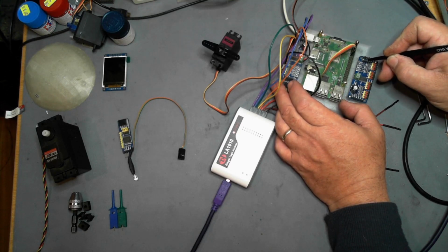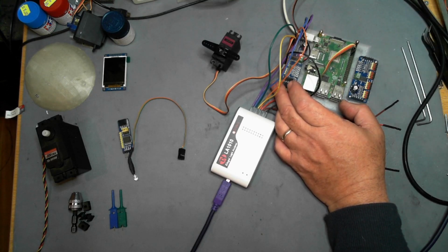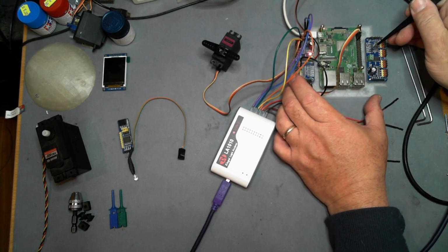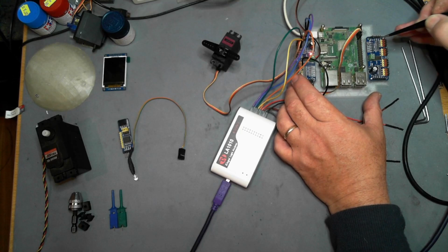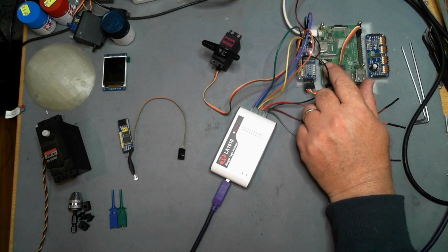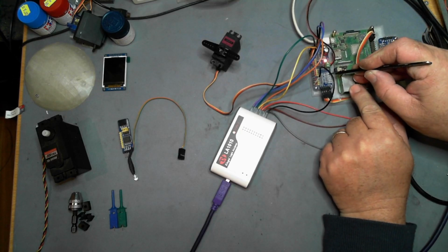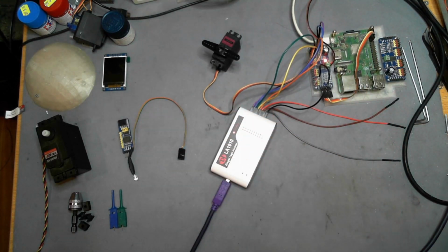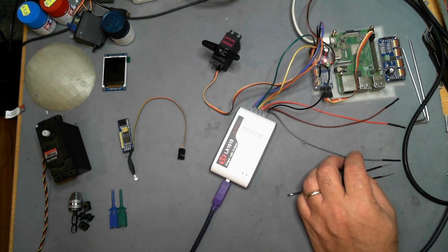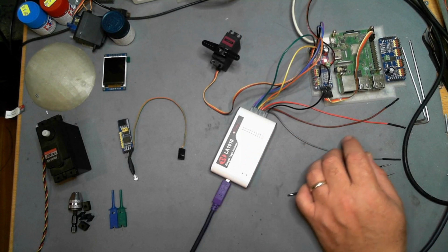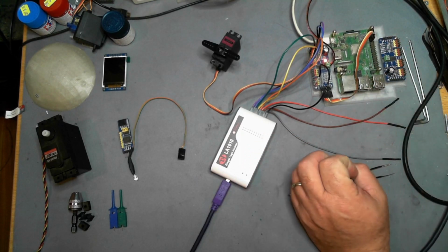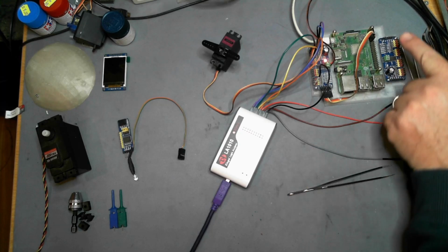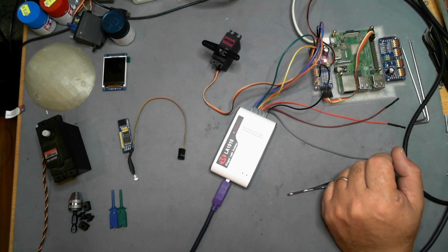If you short both this one and this one, you add 1 and 2 to the address, and so on, each pad being a double of the previous pad. In this case, none of the pads here are shorted, so it's at the base address of 40 hex. So we've got 40 hex there. The I2C bus on the Raspberry Pi is on bus 1. That's the one that's brought out to here that we're using.